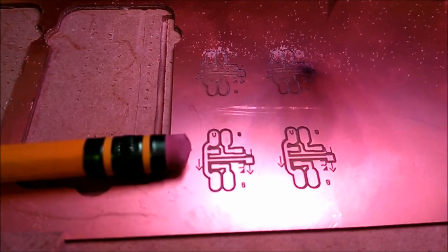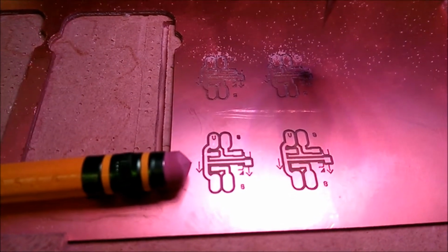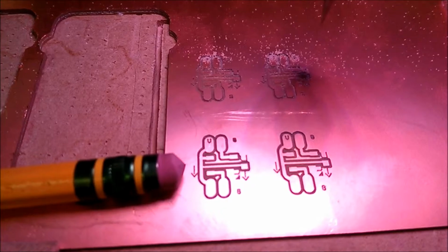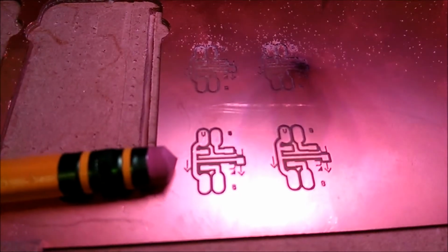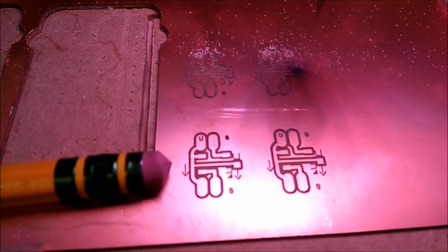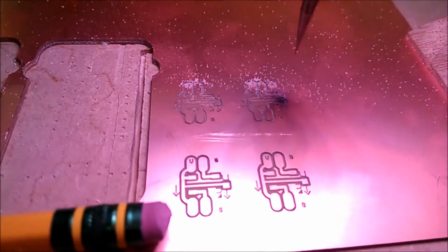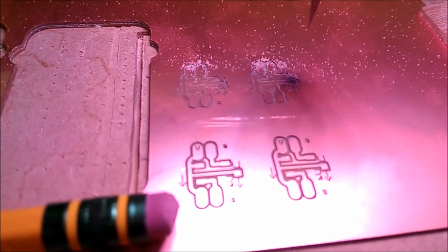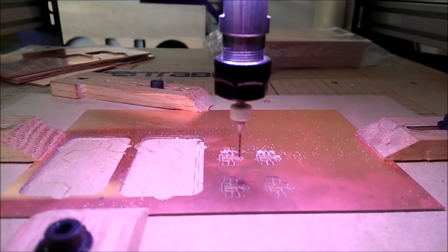Each of those letters, or the width of the line, is probably about 0.3 millimeters. So yeah, you can get super fine detail here with the Shapeoko, and this is not even the finest bit. I could maybe even get smaller lines if I wanted to. We're going to try a higher pitch here in a couple of days, but yeah, I'm going to go ahead and switch to the drills and we'll show you that in action. Okay, so now we are switched over to the drilling bit.